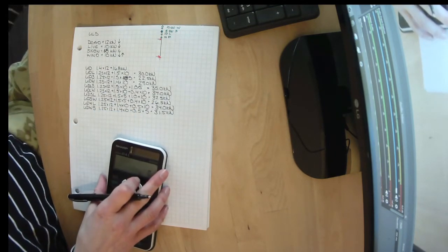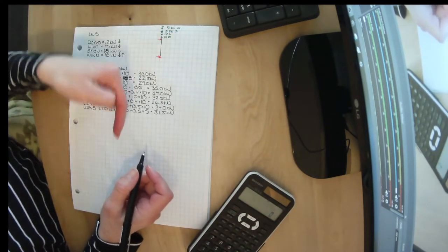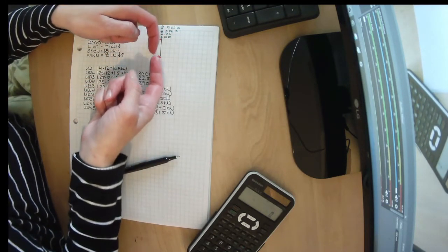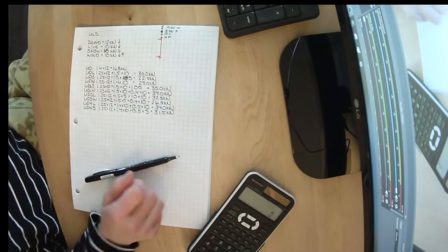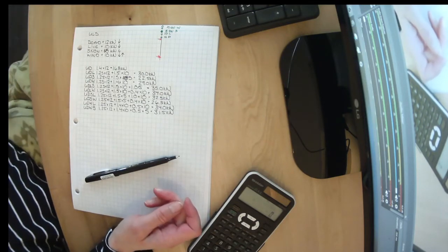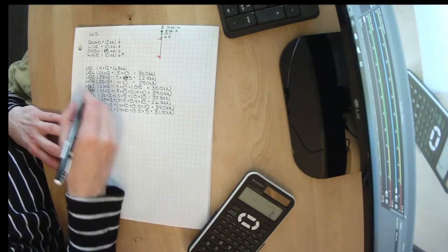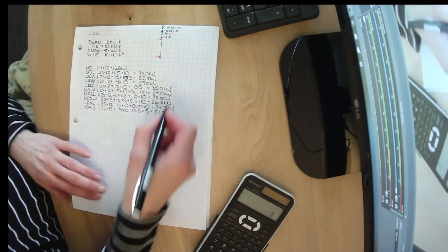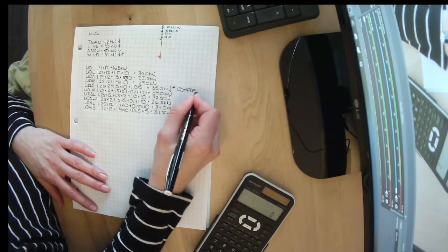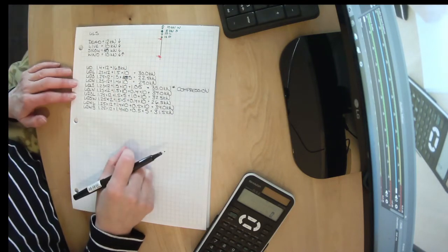Now, if you guys remember, we still had the possibility that wind is acting upwards. So not pushing down, but trying to pull up. And we're concerned about two things. We're concerned about this column compressing too much, but we're also worried about it pulling out too much, or stretching too much, or too much tension on it. So if we're worried about too much compression, these were all the cases where everything was acting down. Well, it looks like the worst case load here was this one for compression, or it trying to push in this direction.